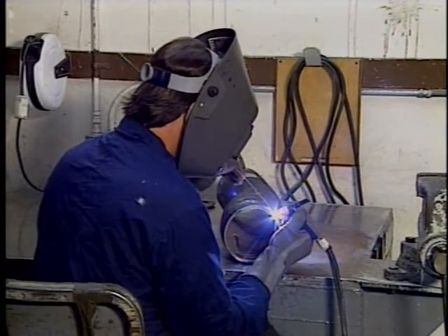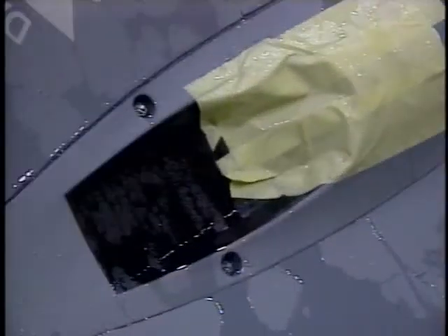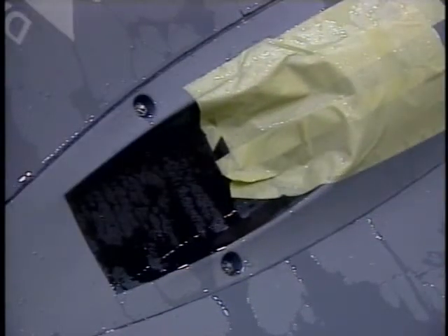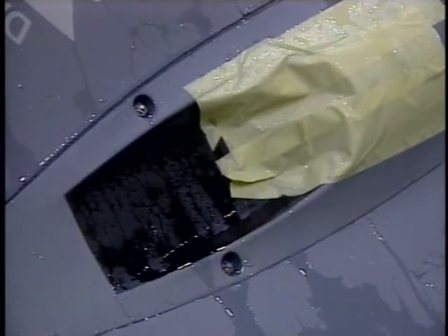Spot-welded assemblies are highly susceptible to corrosion because of water entrapment caused by holes and gaps created between the parts. Engine exhaust areas are often blistered by heat. Gun and missile exhaust surfaces are also blasted away by high-velocity gases and shell casings causing damage to the protective finish. In addition, these areas can become potential water traps.